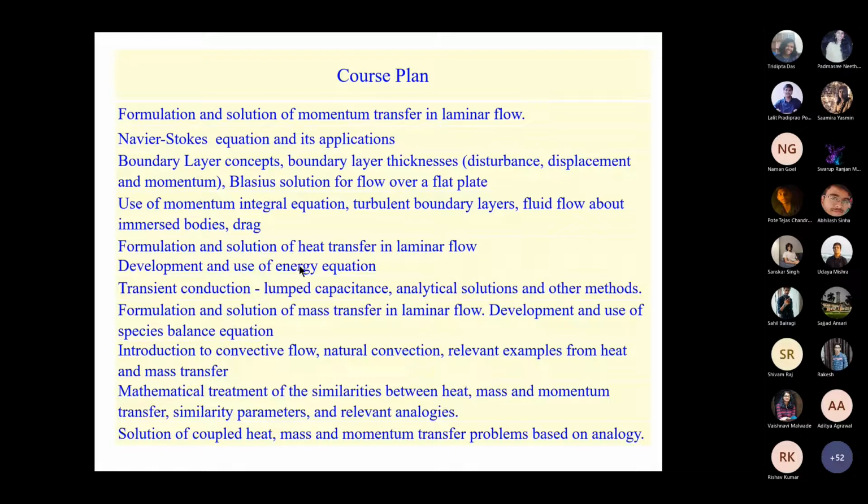So when can we use a simple analysis, which is known as the lumped capacitance model, where the temperature is assumed to be a function only of time but not of space? What are the ways in which we can make such an assumption? You could visualize that if I give you a spherical object at a high temperature, losing heat to the ambient by convection at the boundary, then the temperature can be assumed to be a function of time only and not of space for different cases.